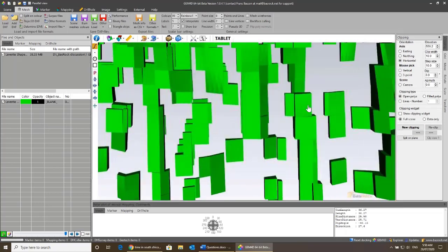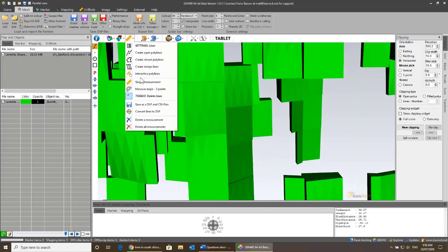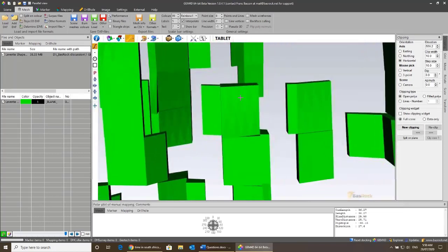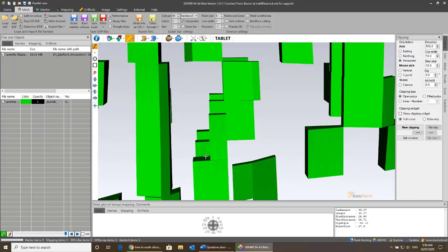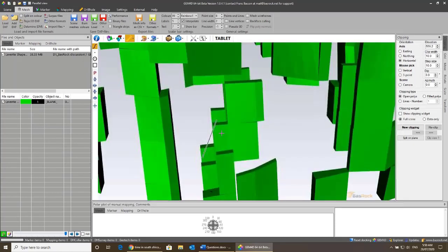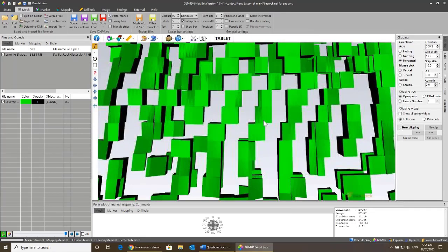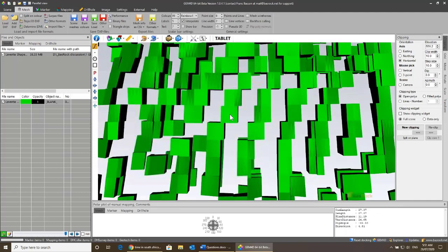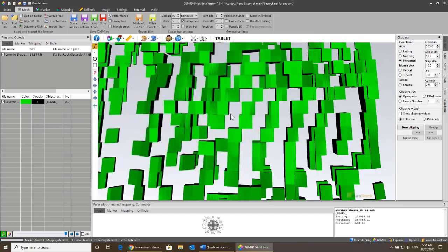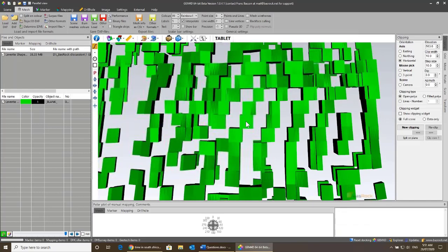I'm just going to check it in another location to see if it's similar. So Control again, so I can move myself about. So I'm going to go to this location. What's the difference between those 2 points? And it is 24.65. So it seems like the interlevel spacing is about 25 meters. I'm going to assume it's 25 meters. So I'm going to go to the center point of any one of these stopes. So I'm going to double click, because when I double click on that center point, then my clipping will automatically go to the correct elevation as well.